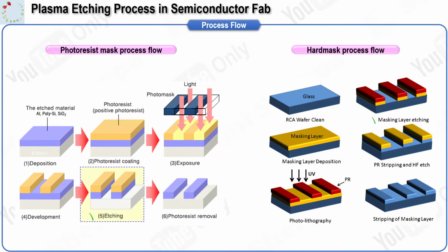Process control relies on accurate endpoint detection and balanced plasma conditions. Optical emission and laser interferometry track the moment when the hard mask opens and when the etch lands on the stop layer. Profile control uses the balance between ion energy and sidewall polymer formation to hold vertical walls while keeping the bottom clean. A hard mask reduces line edge roughness transfer from the resist and reduces profile swing during long etches. Use the photoresist only route for shallow or low selectivity transfers where the resist has enough thickness and durability.